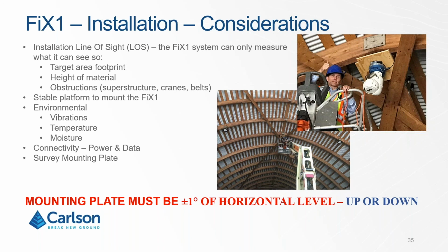Most importantly, connectivity, power and data. When you set it up, is there power and data available? You could get it to run off of batteries or some other power sources, but they will run out over time. So we always recommend going to mains power that you can switch on or off at a safe location, and also data connectivity. You have to be able to tie it into your network. And also you want to survey in the mounting plate if you can.